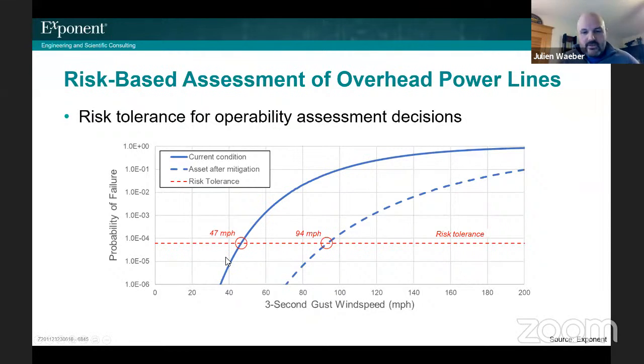And so for your understanding of the condition of your current system, you might find actually that if you don't want to assume any higher risk than that, you'll have to shut your system off at a much lower wind speed in this case. Versus when you first install your system, you know that the system is new, you know that it's resilient, you know that the structural components are, minus errors in fabrication or installation, more resistant to deformation. And so you might be able to tolerate higher wind loads. But that's something that's really important to understand, and you can translate in understanding the full probability of failure with respect to these hazard curves.